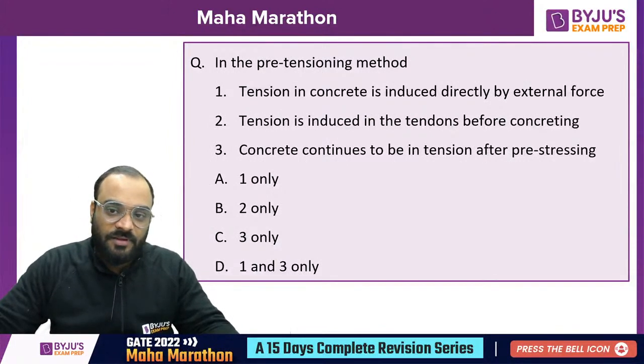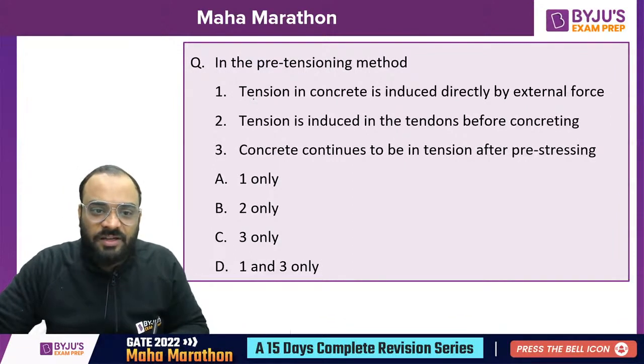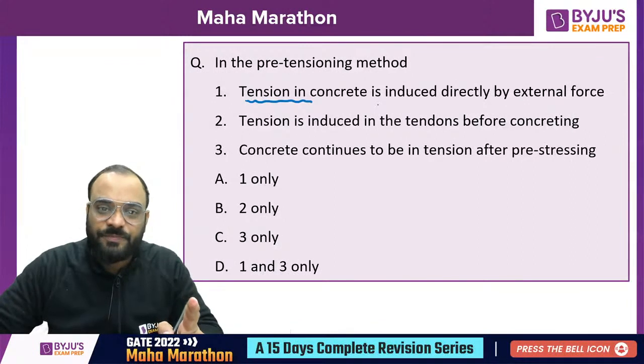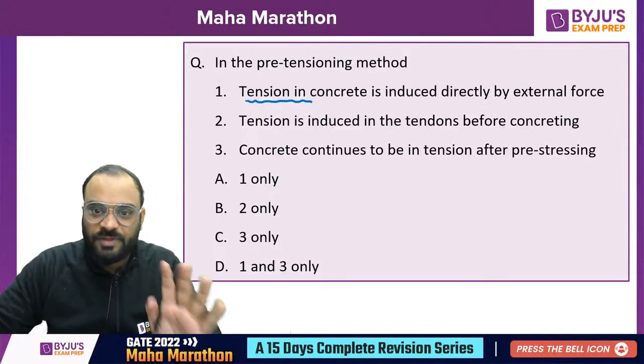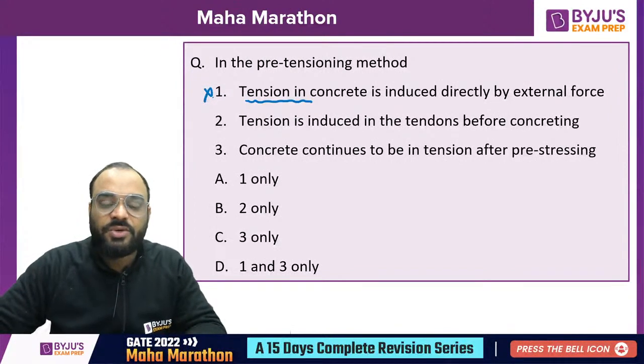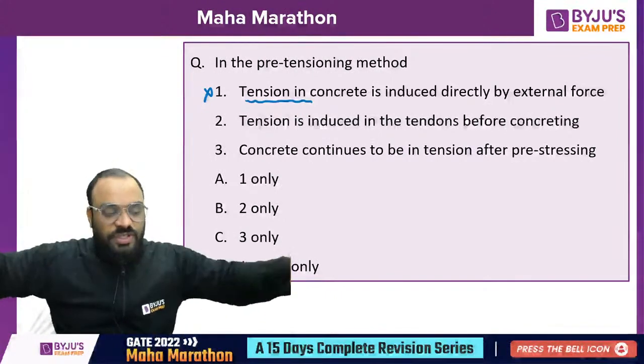Okay. Let's understand, guys. Very simple question. In pre-tensioning method, the tension in concrete is induced directly by the external force? No, this statement is wrong. We are not providing the tension force in the concrete, right? Our task is to give the tension force in the cable.